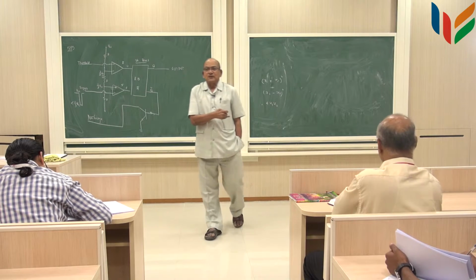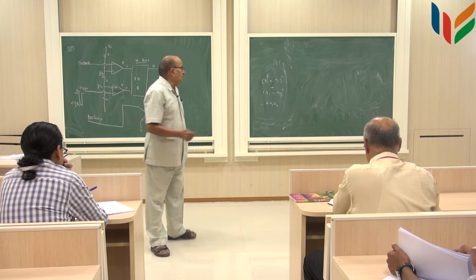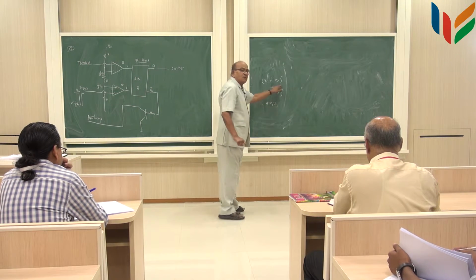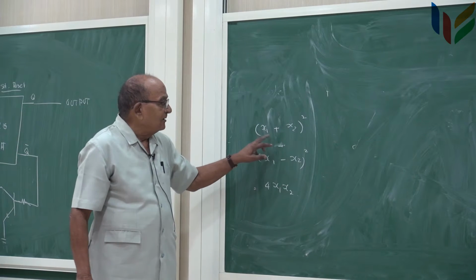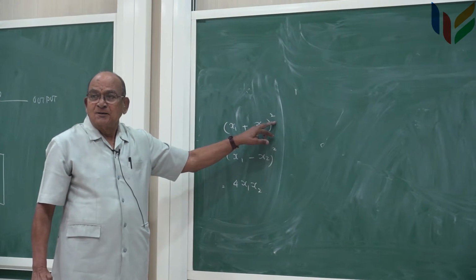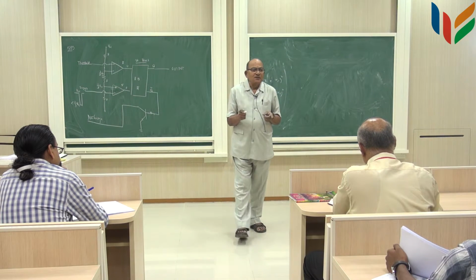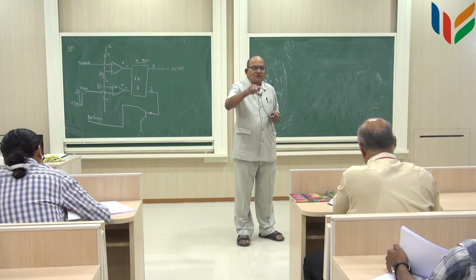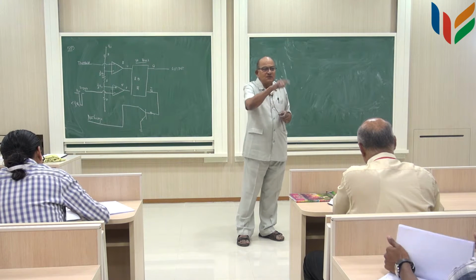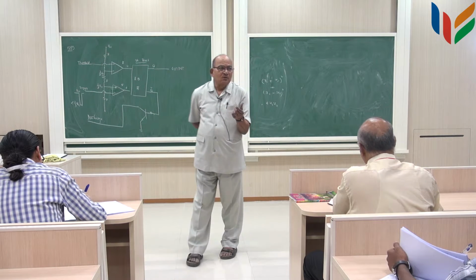So, I can use this mathematics to make a multiplier, because I can add two signals that have to be squared up, right. The squaring up can be done by using a nonlinear device which has a square law characteristic, y is equal to x square, and a typical square law characteristic is a diode.